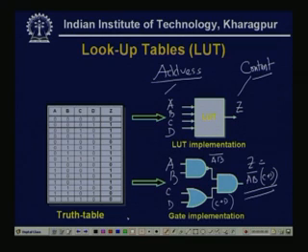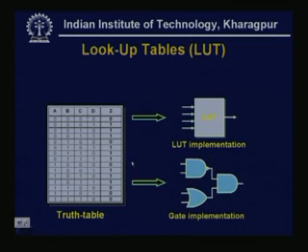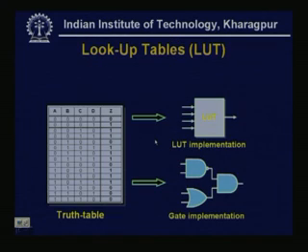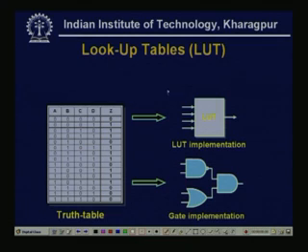Now, the same thing we can treat as follows: if I give the A, B, C, D values, that particular content is already computed and kept as the content of the table. So, mainly this is the basic concept of the FPGA LUT. In a LUT, the inputs are treated as the address, and the output is the content. So, this is nothing but a memory.